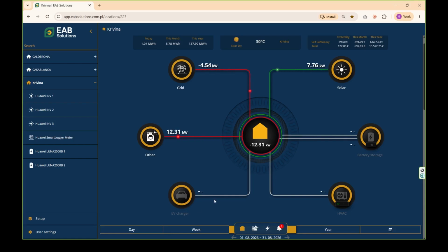You let the system run, and the EMS will learn when the vehicles are plugged in, when they're unplugged, how much they've charged, when the vehicles come back, what state of charge they come back with, whether they've discharged a lot or a little, and how much they need to charge again so as not to run out. The system is constantly learning and knows exactly how many kilowatt hours the charging points need each hour of the day for the fleet to work. And that's what the EMS does.